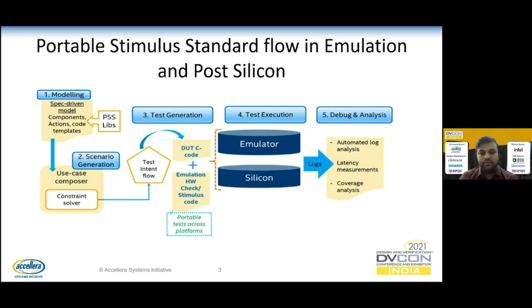We had to develop some small automation steps to validate those log files, and then we reuse the same test content generated here during silicon bring up also. That was our main intent, because the test generation work has to be reused in our silicon bring up. Whenever we face any issues during silicon bring up, we move back to the original test content flow, generate it, and bring it back here to validate our media functionality and performance.